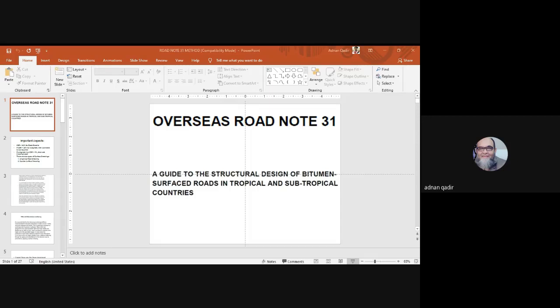Mixes which are designed to have good durability rather than high stability are flexible and are likely to have sand and bitumen contents at the higher end of the permitted ranges. In areas where the production of sand size material is expensive and where there is no choice but to use higher stability mixes, additional stiffening through the aging and embrittlement of the bitumen must be prevented.